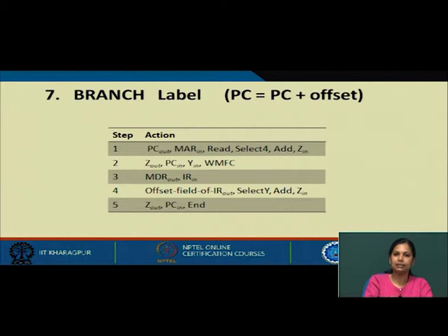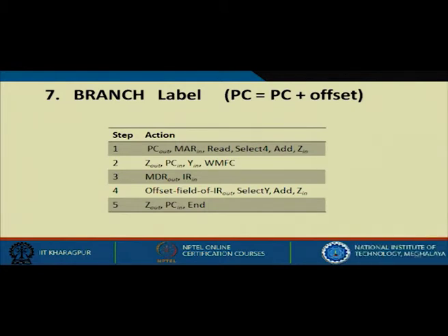In any instruction, whether it is a branch, add or any other, in the fetch phase we do not know whether it is a branch instruction or not. So, in any case we are incrementing the PC value, but after decoding the instruction we will know that this is a branch instruction. Once I know after decoding that this is a branch instruction, we need to load the value of the PC with the branch address. That offset needs to be calculated first, and then it should be loaded into PC again. So, let us see what steps are required for this purpose.